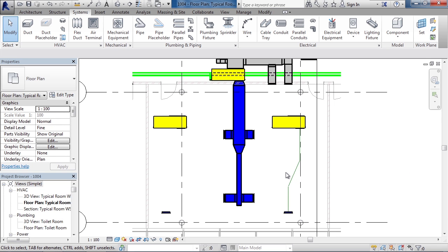Basically, it's the same thing, except it's only being represented by a single line. Typically, it's used in conceptual design if you're just conceptually laying out that duct arrangement or that duct line. It still does connect to your diffusers and your air handling units. But the difference is it doesn't have justification values, simply because it's just a line. It also lacks information for insulation or lining, whereas a regular duct would have that information. But as far as placement, if I'm manually clicking points, it is placed the same way as a regular duct.